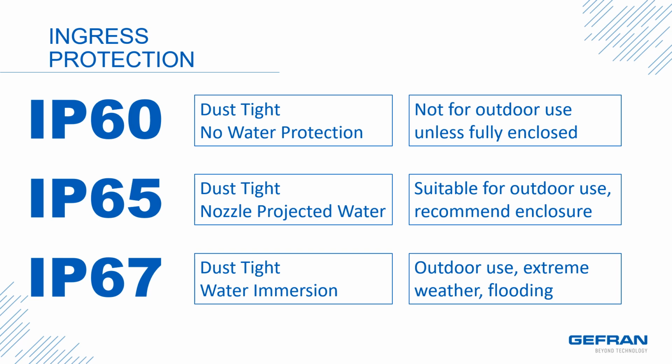IP65 is dust tight and is rated for nozzle projected water. These are suitable for outdoor use, but we recommend applications that provide some additional protection. IP67 is dust tight and is rated for water immersion. These are suitable for outdoor use, extreme weather, and flooding.